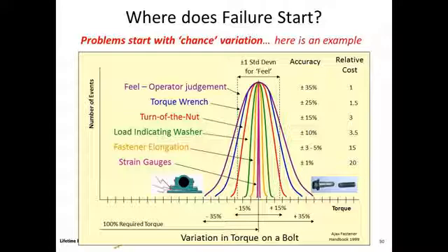You can improve that if you do the right torque wrenching techniques, and there are particular methodologies to use to get that down to plus or minus 15%. But you've got to do it a particular way and follow that way every single time. Nonetheless, if you have a torque wrench as your preferred way, then you will occasionally have snapped fasteners and loose fasteners, even though you're using a torque wrench.